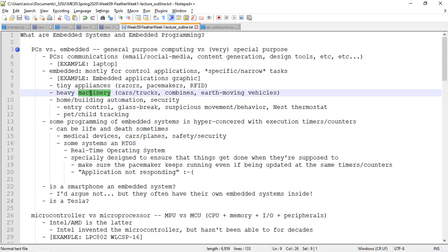So that's basically how execution of a Python program in an embedded system differs. I've already talked about the outer while loop, and a lot of stuff you'll see inside that while loop is typically a bunch of if statements that are testing conditions that may have happened such that something needs to happen in response. Something happening is generically called an event. So this style of programming is, rather than straight line programming, like reading a file until all the data is gone and then closing it and being done, called event-driven programming. So things happen when events happen, and nothing happens until an event happens.